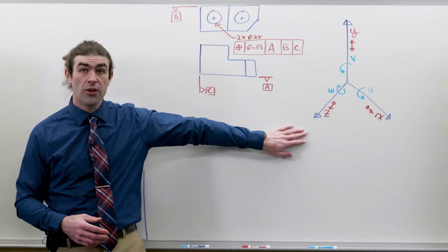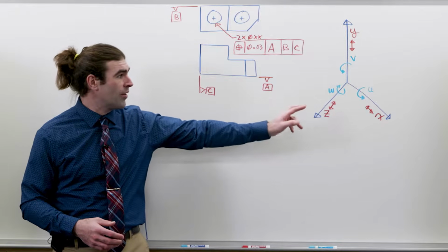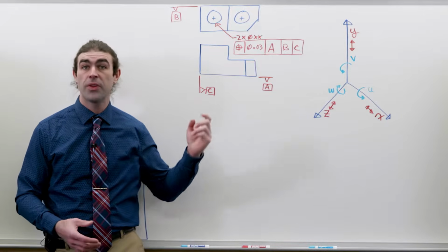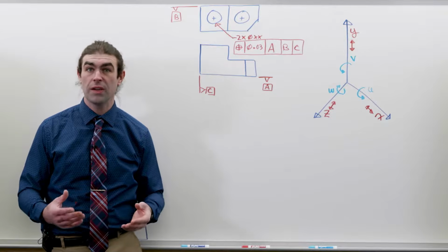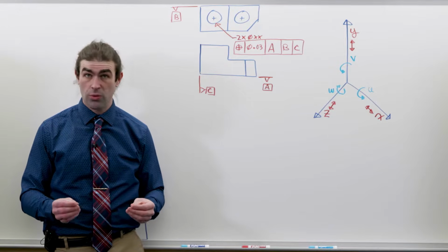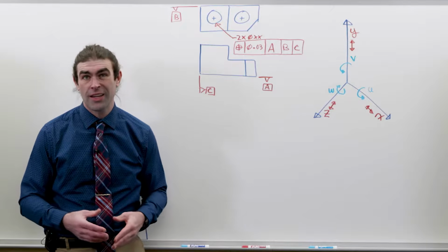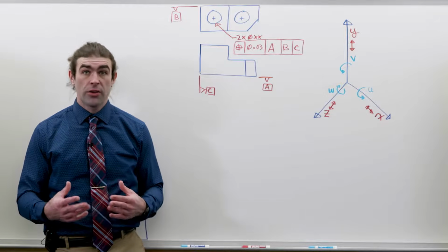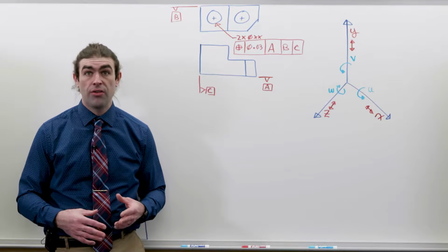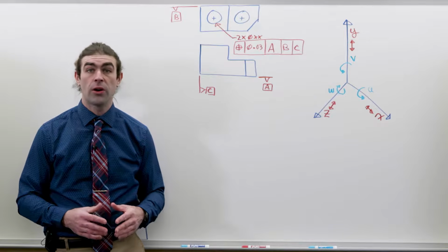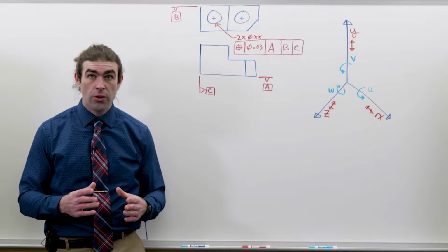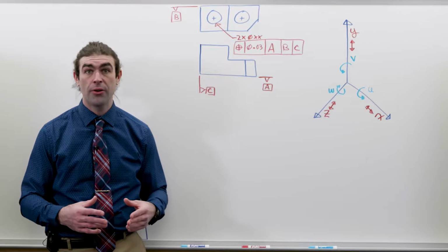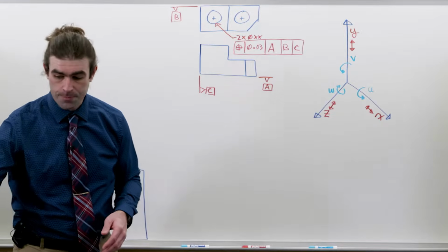Now, our datum reference frame looks like so. We have one direction in x, another direction in y, another direction in z. This is our 3 dimensions, and it's what we usually need to measure parts. If parts are really, really thin, like sheet metal, sometimes you only need to worry about 2 dimensions, the x and the y. Now, there's another concept called degrees of freedom. This is really important for inspection. It is the order in which you constrain the feature so that the feature doesn't move around on you while you're inspecting. Let me show you how it works.